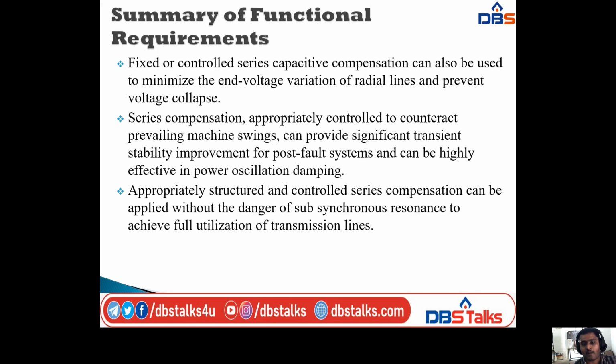Series compensation appropriately controlled to counteract the prevailing machine swings can provide significant transient stability improvement for post-fault systems, that means after the fault clearing, and can be highly effective in power oscillation damping.